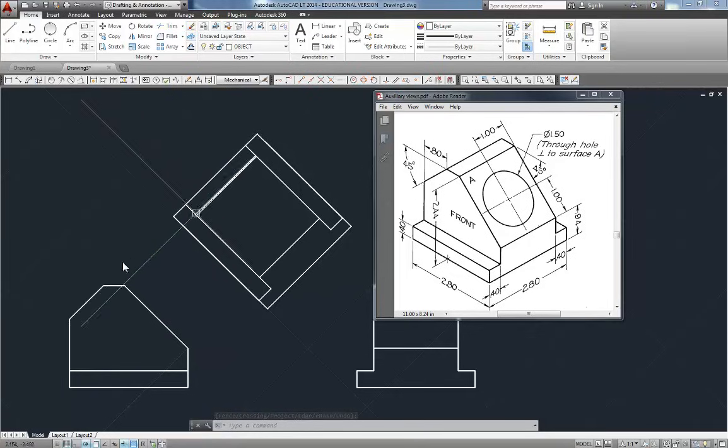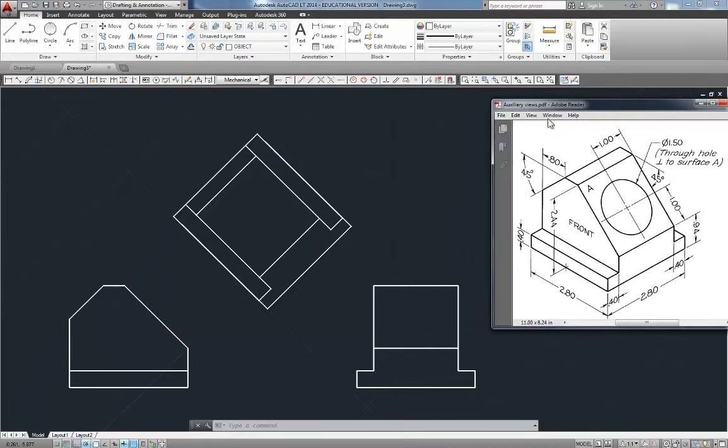This little foreshortened surface here is the top. Again, let's get this back out of the way. It is this wide. So I should see it that wide. Notice the line doesn't keep going. That's what we want to see. Here's the back surface, and I know that this back corner back here, that's this surface, this edge. This corner is only the width of this view in here, right? It's not the full width. So in spite of this corner that we see out here, it's not really there.